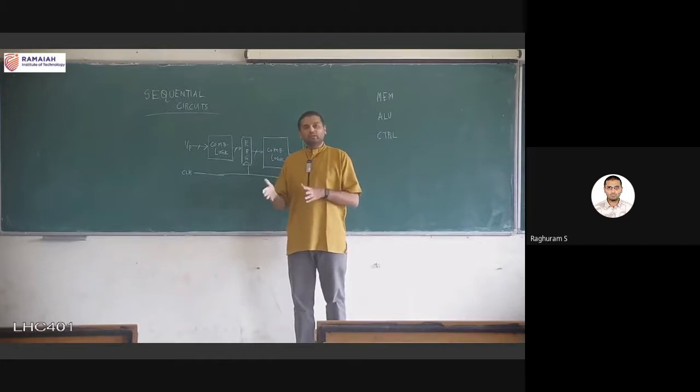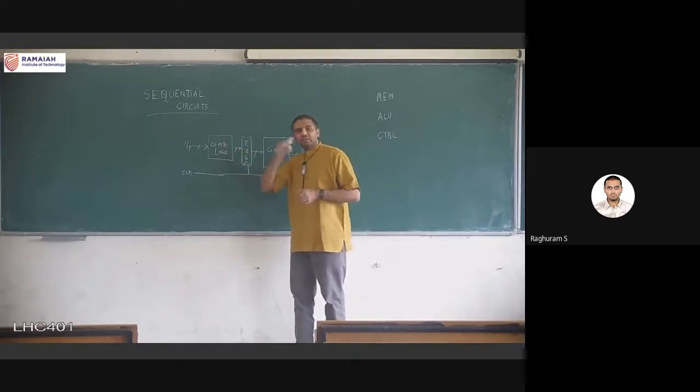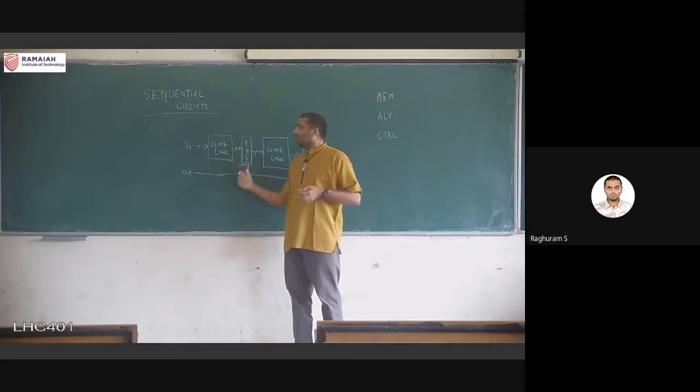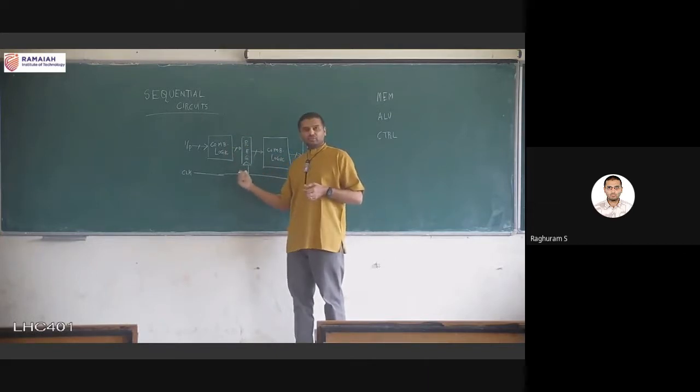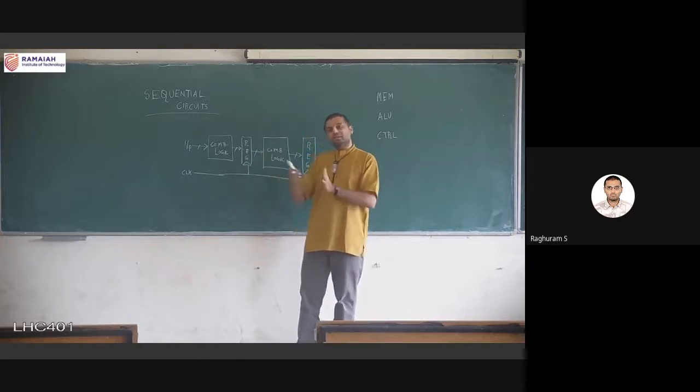So after 2 nanoseconds, all the outputs here are ready, then the clock edge will come, and then this will be sampled and stored in this register, okay. And once it is stored in this register, this block will be seeing the output and it will be doing something during the next clock cycle.